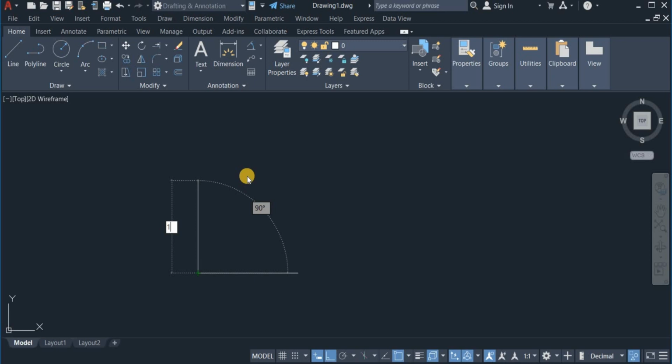So I will enter 10 on the left banner, then toggle to the right to enter the angle. You can see that the banner has a blue background and it's showing 90, but I'm going to make this line incline at an angle of 45. So I'll enter 45. Okay, and enter.